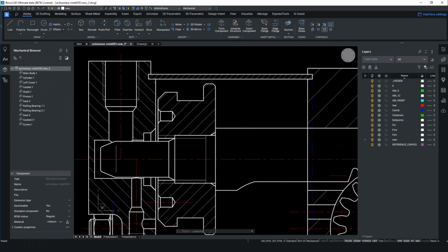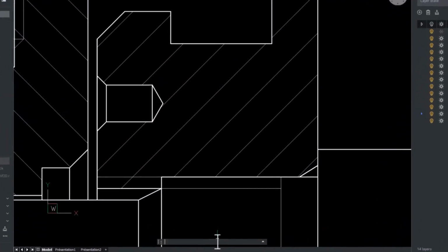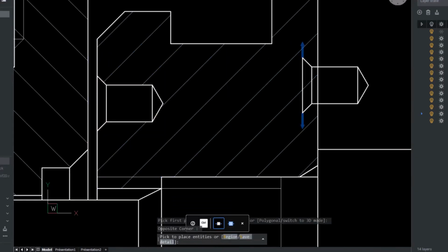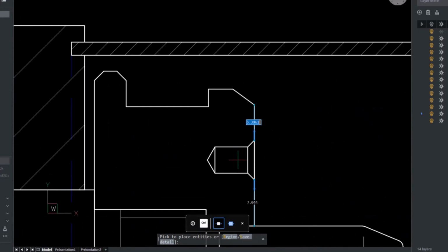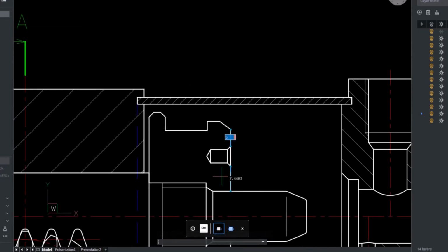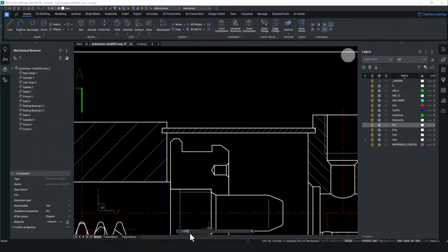To optimize the design process, we'll use the intelligent copy guided tools to copy blocks from one place in the drawing into another. Copy guided automatically aligns copied entities with relevant geometry using temporary guide curves. Polyline segments and multi-line segments are also accepted as guidelines.